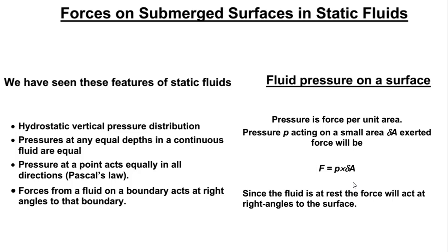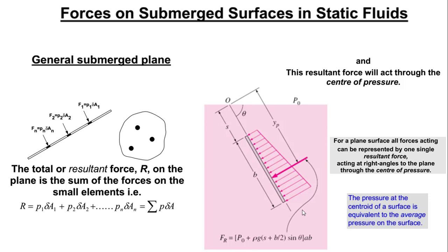In other words, pressure is equal to force per unit area, and force is equal to pressure multiplied by the area. Since the fluid is at rest, the force that we calculate will be acting at right angles to the surface. These are the basics of static fluids that we need to keep in mind every time. Whatever we calculate has to be based on these facts and theorems, from Pascal's law to hydrostatic laws and all the things that we have looked at before.